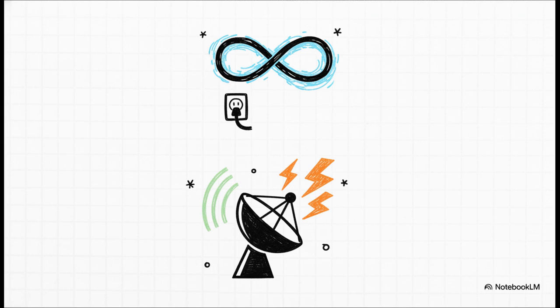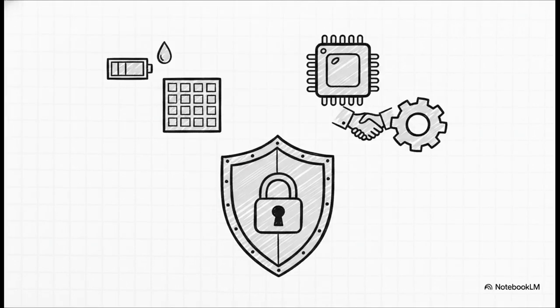Difference 2, they must react to unpredictable environments. A desktop application essentially controls the pace of user interaction, but a real-time embedded system has to concurrently handle both expected periodic events and completely unexpected, unpredictable events at any given moment. Now, what's really fascinating here is how the physical world dictates the software. Difference 3 highlights severe physical limits. You might have crazy strict constraints on battery power, physical size, or weight, which forces you to write incredibly efficient code. Difference 4 is direct hardware interaction.